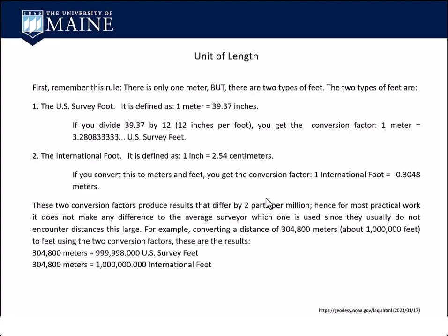So in the future, you realize that's a US foot, and you'd have to go back to meters and then convert to whatever the new conversion factors are, or if they're going to use the same for the international foot. I haven't seen any numbers, so I'm not sure. But just remember that every elevation they ever established was in US feet.